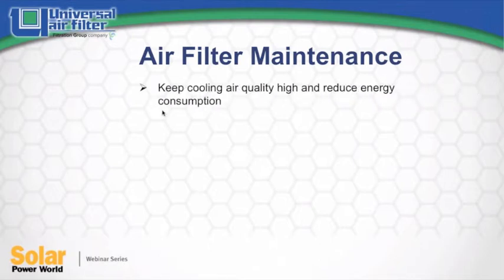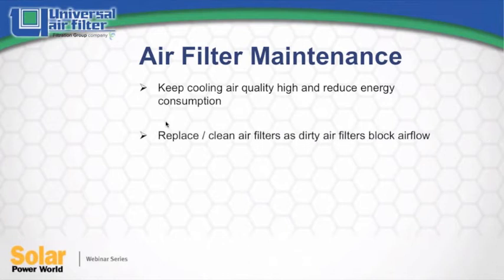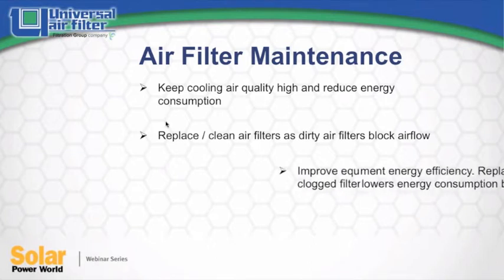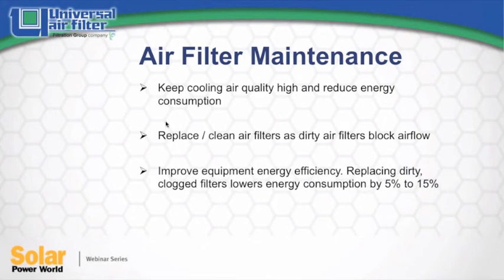The message with maintenance is to make sure you have preventative maintenance procedures in place to check filters and clean and replace on a regular basis. Clean, cool equipment performs most reliably. Energy efficiency follows, and you can lower your energy rates by 5 to 15% by eliminating clogged filters from your systems. The most important point is to eliminate energy production failure.